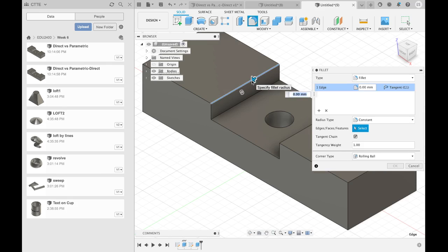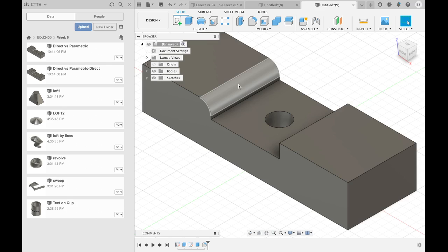Click, and once you click, you see the mouse and this dialog. You can move the mouse, or you can type the number. This number is a radius from the center line. We want to make a smooth surface. So the value was 7.5. You can type enter. We made one fillet on this side, and then we are making this side.